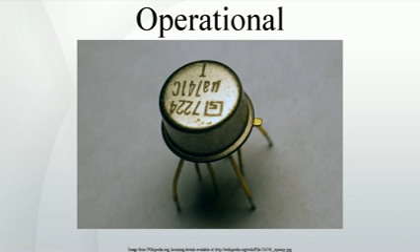1972, single-sided supply op-amps being produced. A single-sided supply op-amp is one where the input and output voltages can be as low as the negative power supply voltage instead of needing to be at least 2 volts above it. The result is that it can operate in many applications with the negative supply pin on the op-amp being connected to the signal ground, thus eliminating the need for a separate negative power supply. The LM324, released in 1972, was one such op-amp that came in a quad package, 4 separate op-amps in one package, and became an industry standard.